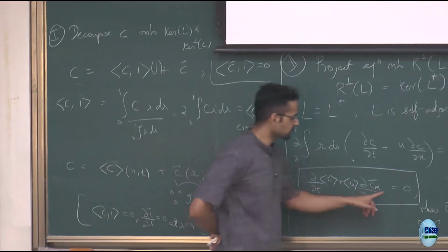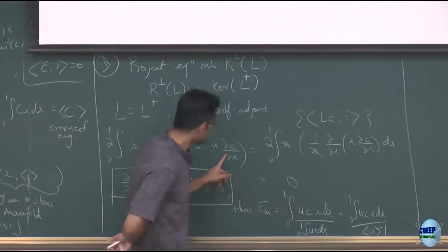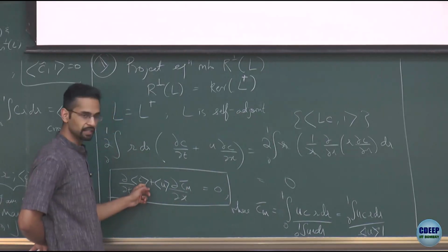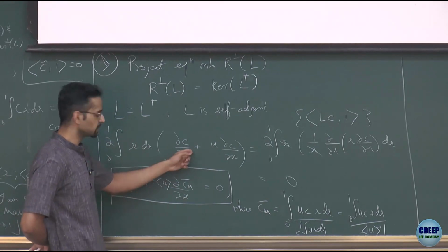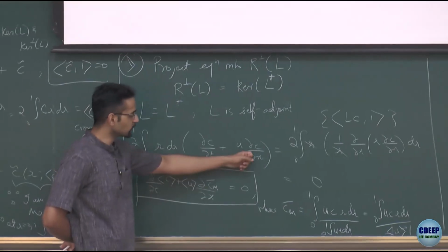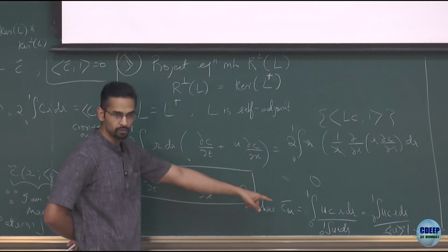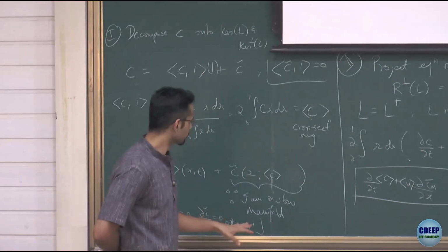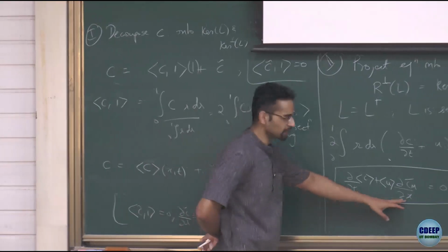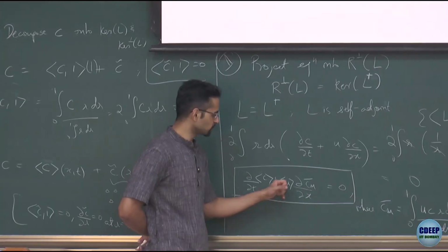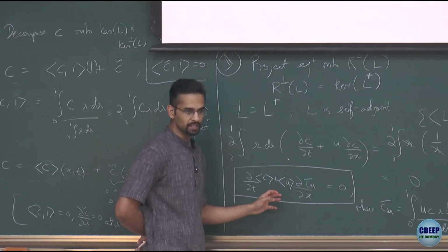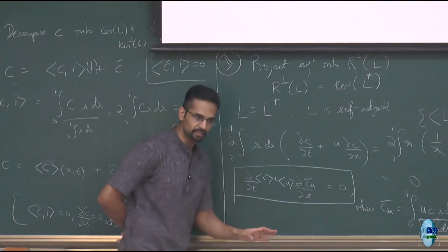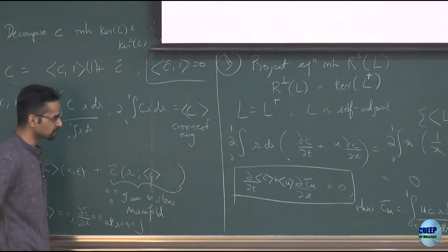Because over here, I still have this integral. That's the integral I had here. I really need to replace C by C average plus C tilde. That C tilde doesn't play a role in this term because I would take the integral of C tilde, which becomes 0. So C tilde only survives here. Why? Because it gets multiplied by U. So the integral of U times C tilde is what I need to close the equation. So in other words, I have to find C tilde. I'll just reformulate it in a way that's physically more intuitive, because you have the time evolution of the cross-section average depending on the advection of this cup mixing average. In chemical engineering literature, these two kinds of averages are popular for various reasons.